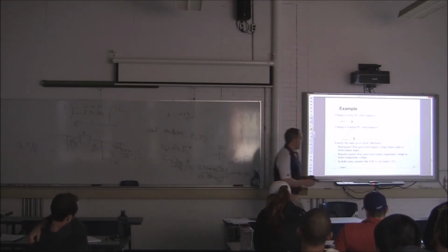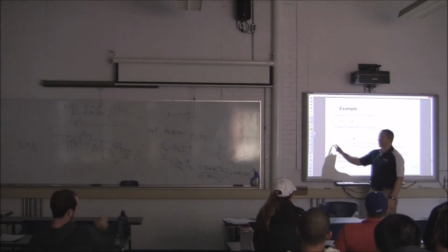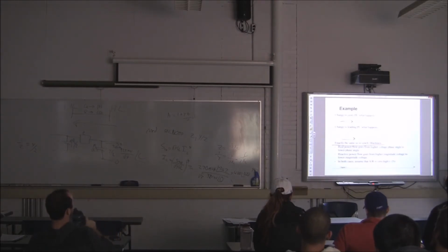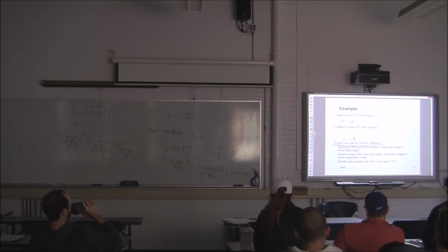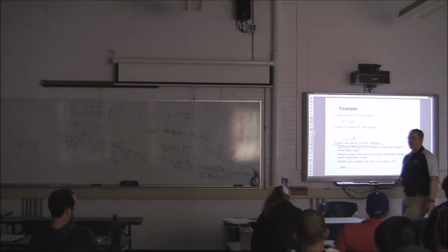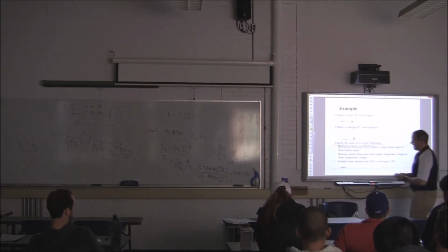And this, if you had taken a previous class with me, isn't it exactly the same as in synchronous machines? When we talked about excitation systems, that's how synchronous machines work. What's the X over R in a synchronous machine? It's almost infinite, right? X is much, much higher than R in synchronous machines, and oftentimes you don't even bother showing the R. It's so much smaller. So this sort of validates what we would expect.